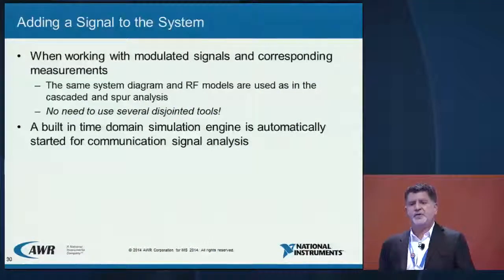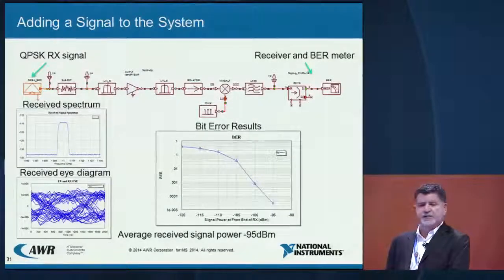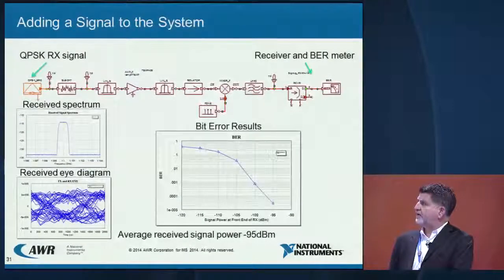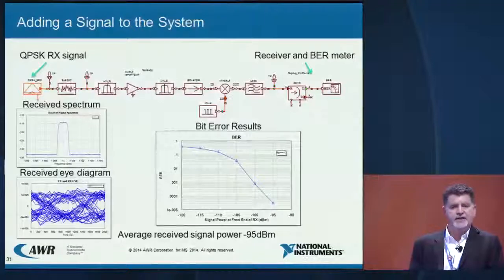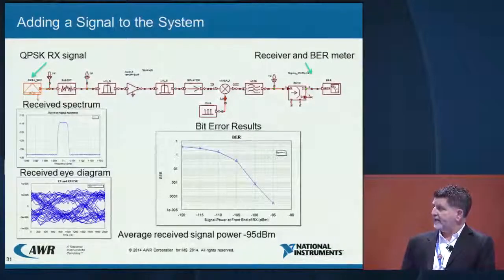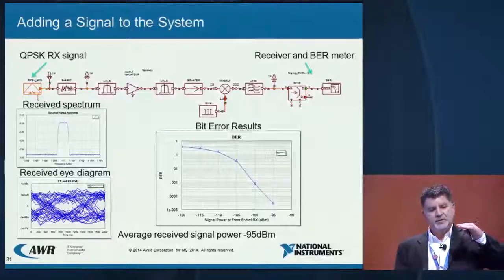VSS supports many different measurements. It has two simulation engines in it. Once I switch to a communication standard, not only does the frequency domain analysis continue, but now we can look at time domain measurements, such as receiver sensitivity or bit error rate, and eye diagrams, and spectrums. So from concept to a closer hardware implementation, all achieved in one tool. I'll leave 3 minutes for questions.